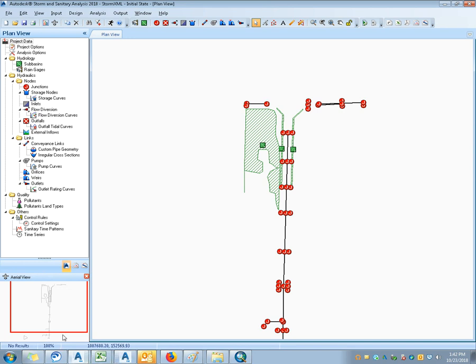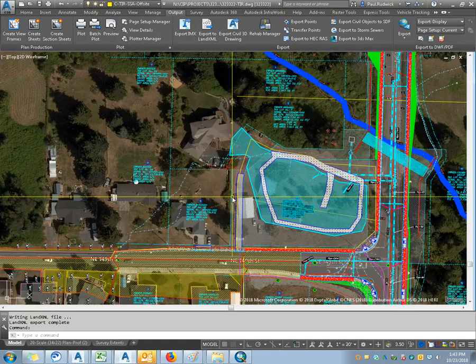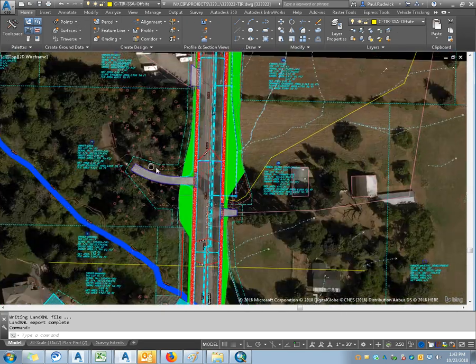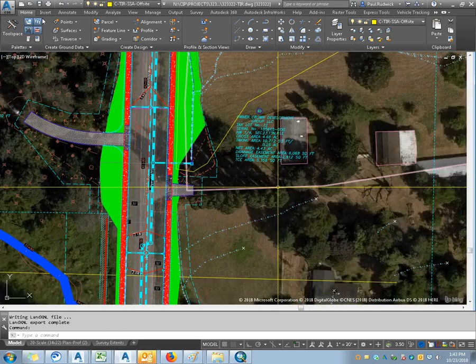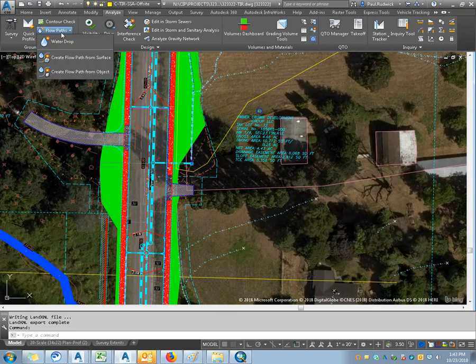Now, the second option I'm going to talk to you about is one you'd think would make the most sense to use. Because I think when people made this specific Civil 3D element in CAD, this is what their goal was. They're called catchments. Catchments are part of the analysis tools within Civil 3D, and you can see all these little flow paths that I've already drawn in here.